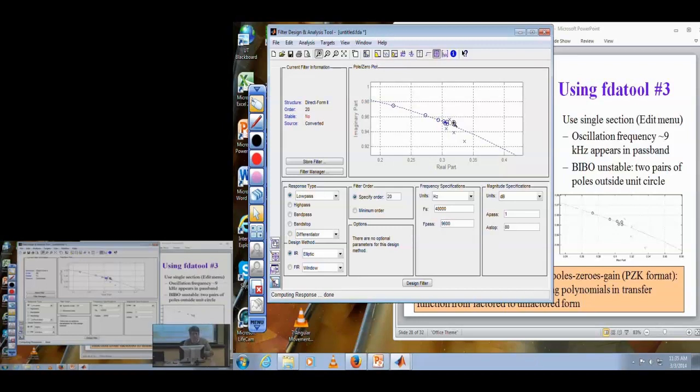Well, a zero on the unit circle actually will eliminate that frequency. On the zero away from the unit circle, if it's really close, it doesn't matter whether it's inside or outside. It's the distance from the zero to the unit circle that matters. So if the distance is the same, it doesn't matter whether it's inside or out, much, in terms of its magnitude response. At the frequency of the zero, the magnitude response wouldn't change, whether the zero is inside or out. Now, as you go around the unit circle, whether the zero is inside or out does have a slight change at other frequencies.